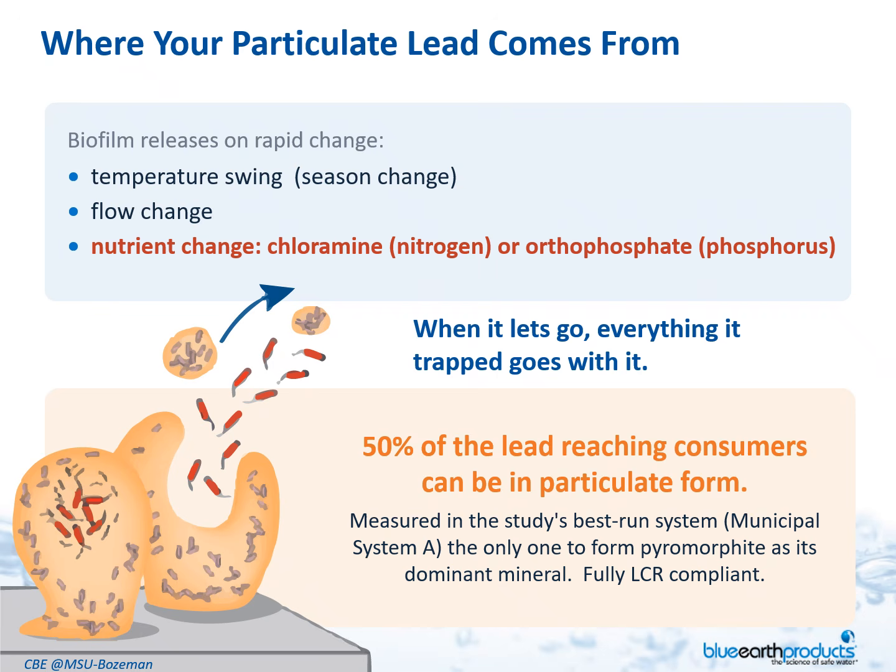These are nutrients. And even in our cleanest system, which was actually a municipal system, not a facility system, 50% of the lead reaching customers was in a particulate form. That means that lead was not following the rules of the lead and copper rule, or the chemistry of the lead and copper rule. It was being accumulated in biofilms and being sloughed off in particulates.